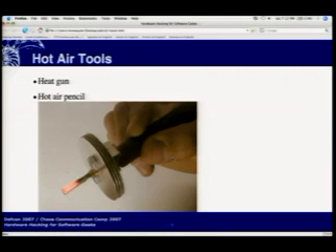Another type of hot air gun is for a completely different purpose, but they've got these wire sleeves that shrink around connections for if you're putting sleeves to attach a wire to a pin. You don't actually need a hot air gun for those. You can just take a big lighter and shrink it to the wire that way without spending $90 on an overpowered hairdryer.